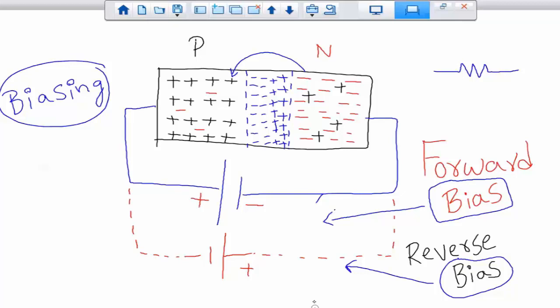What about when you're doing it in reverse bias? If it is in reverse bias, then there is not going to be any current flow except what we call leakage current. Again, this comes under chapter 2. Reverse bias means, perfectly speaking, the current is 0 amps.